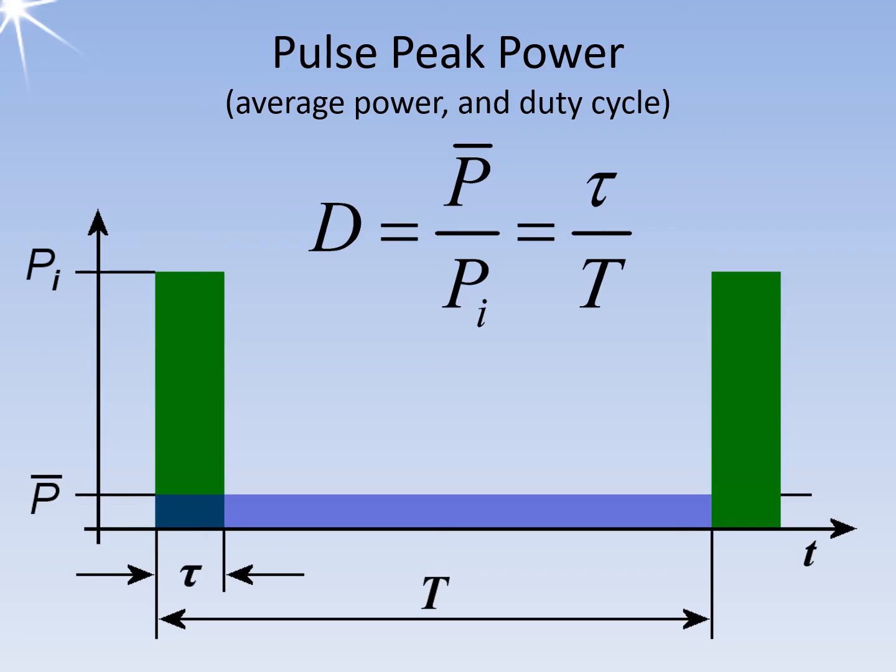The duty cycle, D, is the ratio of the pulse duration to the pulse period and the ratio of pulse power to average power. Formally, the impulse power is not of such essential importance, but rather the energy contained in the pulse. Power is energy per time unit. If we assume that the echo pulse has the same duration as the transmitting pulse, the ratio of the powers is equal to the ratio of the energy quantities.